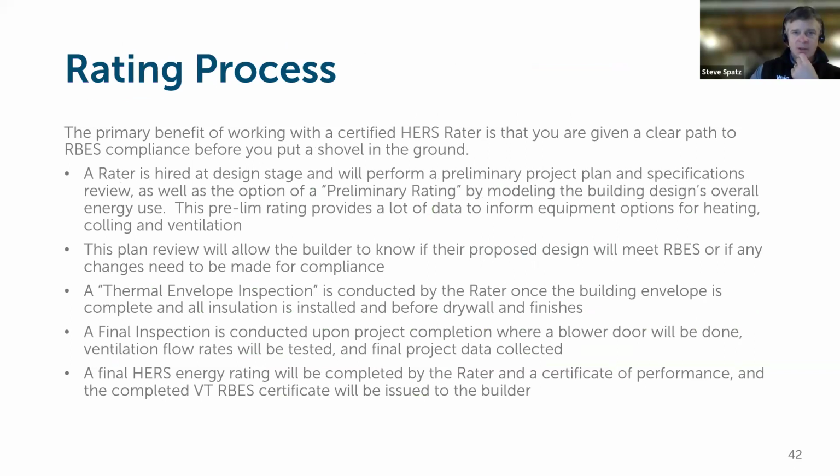So the process of having a rating done, if you've worked with us previously in our new construction program, then you work through the HERS rating process, and you're hiring a rater ideally at the beginning of the construction design process. The HERS rater is an integral part of the construction team, where the rater is reviewing the plans and specs while still on paper and doing a preliminary rating, taking those performance specifications and the building component information, the full plan set, and putting that into the modeling tool.